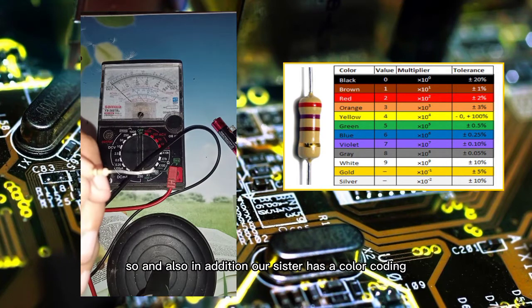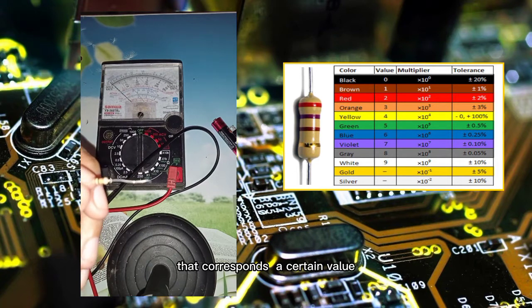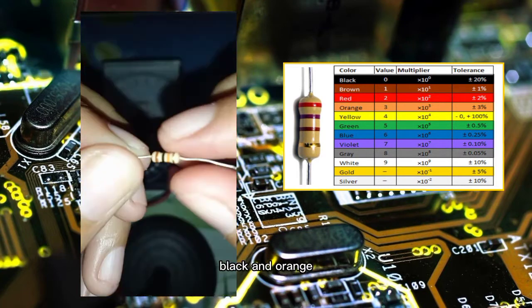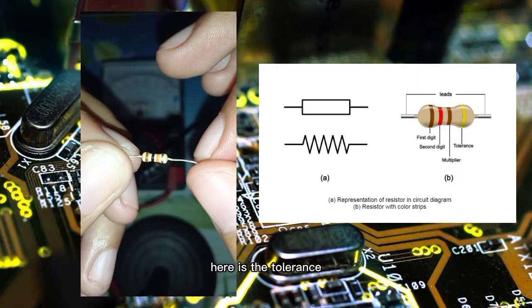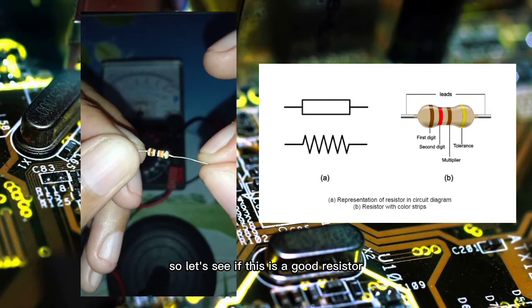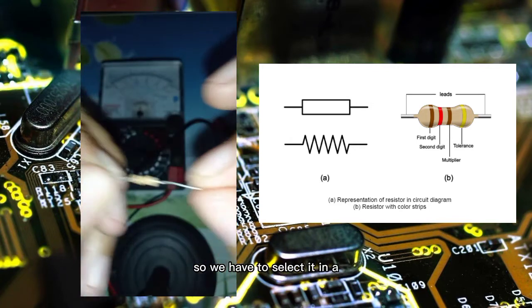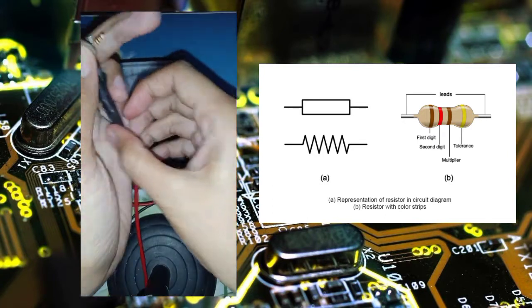And also in addition, a resistor has a color coding. There are 9 colors that correspond to a certain value. And we have brown, black, and orange. And you see this gold here is the tolerance, then the first digit and the second digit. Then the multiplier is the orange. So let's see if this is a good resistor. Let's check. So we have to select it in 1 ohm.